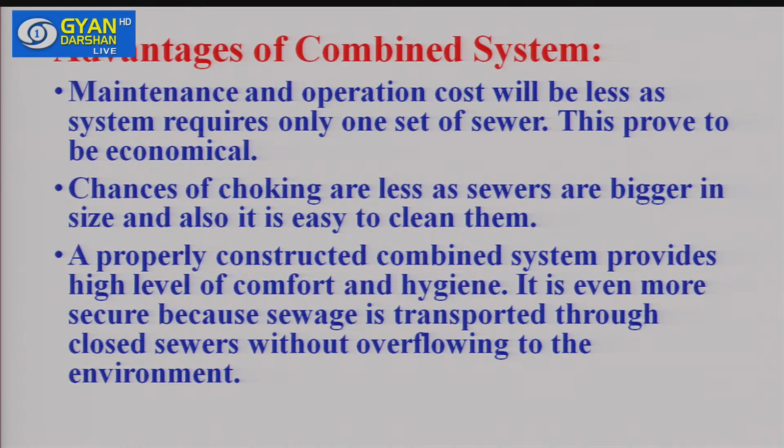Then what are the advantages of the combined sewerage system? Let us see the advantages. The maintenance and operation cost of this combined system will be less, as the system requires only one set of sewers. This proves to be economical. Chances of choking are less, as sewers are bigger in size, and also it is easy to clean the sewers.